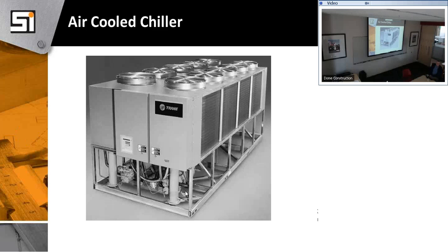Yep, the evaporation, we call it cycles of concentration, so I have to keep draining water, because you keep evaporating, and if you don't get rid of the minerals, they just keep accumulating. So I have to keep my cycles of concentration down. I'm bleeding water, so I'm bleeding what I'm leaving in the tower basin. And what's the number one? Owners don't take care of this well. You know, this is where the problems are.